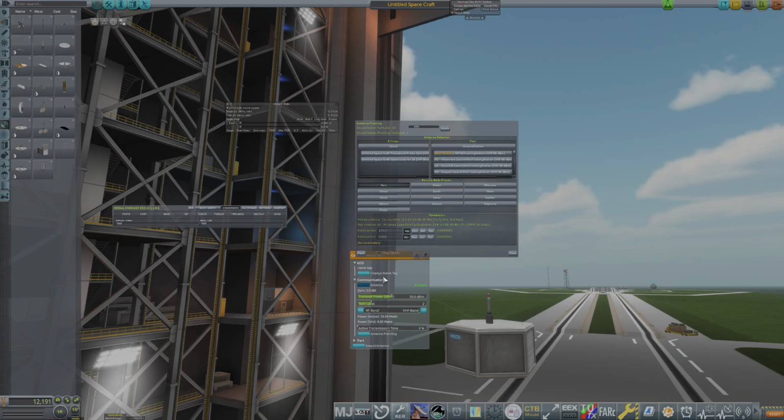Switching the antenna to VHF, you have to select the ground station again because it differs now in the band. And now you can see we actually have a connection. So switching from the UHF band to the VHF band, we took the bandwidth down, so we transmit less data per second, but the range is longer. And this is enough for 30 decibel transmit power on that antenna to actually get a connection in this low geostationary orbits to anything that is flying down in low Earth orbit.